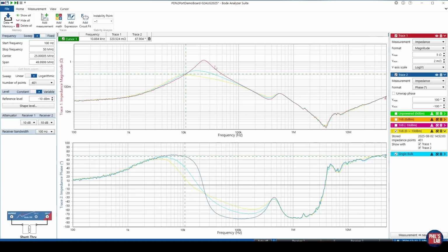Now we're getting more and more of this peaking because of the interplay between the output impedance of our VRM, of our LDO, and the bulk capacitance in that region, because we now pretty much have no bulk capacitance, and you can see impedance magnitude is now even peaking over 1 ohm. So that frequency at around 20, 25 kilohertz, we have 1 ohm of equivalent series resistance when we have load transients at that frequency.